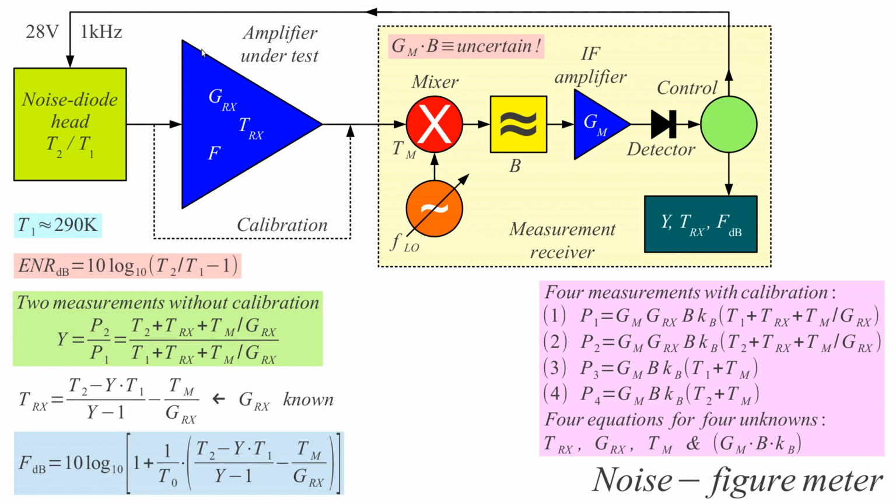In our testing we also have measurement receivers, and these measurement receivers have a mixer, contain much additional gain in the IF amplifier, and contain a filter. So we can bring here just an amplifier without filters and with enough gain because we provide additional gain here.